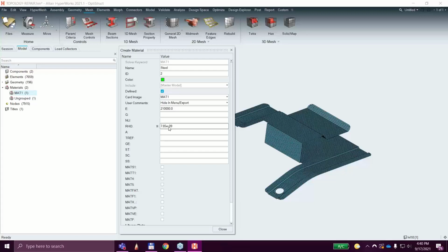And the reason for that number is because the density is going to be in terms of megagrams per cubic millimeter. And all of that derives itself from the unit choice, from the millimeters, newtons, and seconds. If you are really having difficulty wrapping your head around unit consistency, if you Google the term unit consistency, there are some excellent papers out there and excellent charts describing unit consistency and even giving you samples of the popular unit schemes and some numbers in them that will help you out.